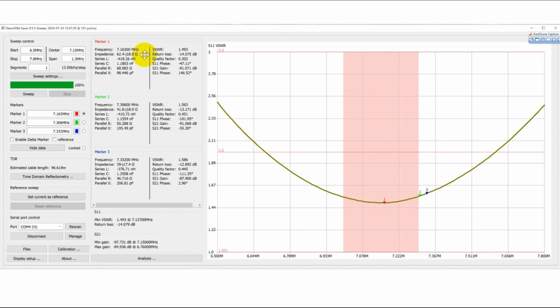So that means that the SWR is going to be a little bit different. You can tune the remainder out of this and bring it down to 1:1 using the tuner in your radio, which will work very well. So those are the charts.